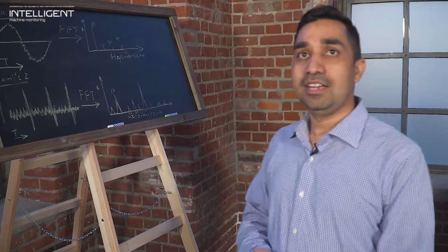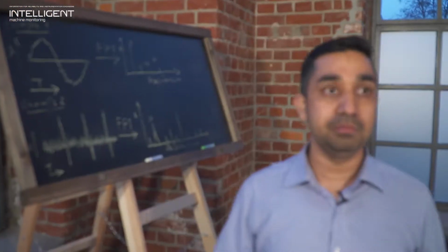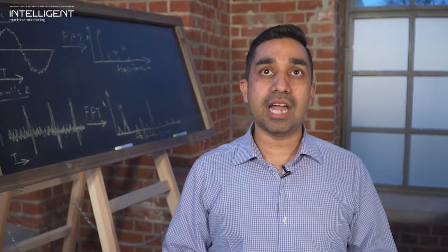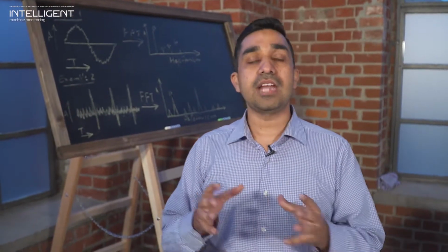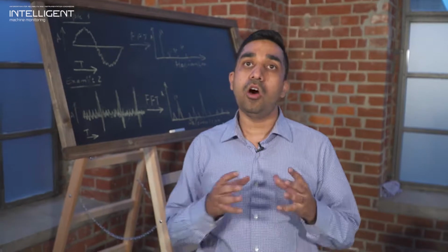So let's get started. Today, as we know, time signal is the basis of all the analysis. In other words, all the analysis plots like envelope spectra, FFT spectra, time synchronous averaging spectra, all are derived from time signal. Time signal gives you much more information than any other plot because it's the root of your analysis. In fact, in some cases, if we compare time signal with FFT spectra, time signal reveals a much clearer indication or gives a much clearer hint of the problem.